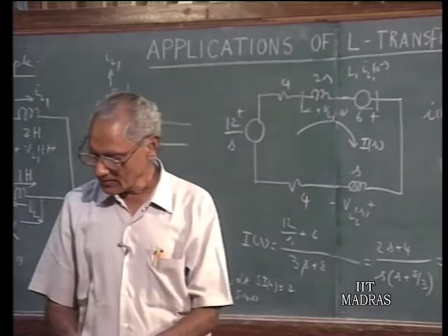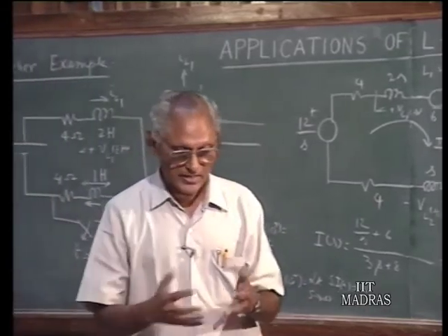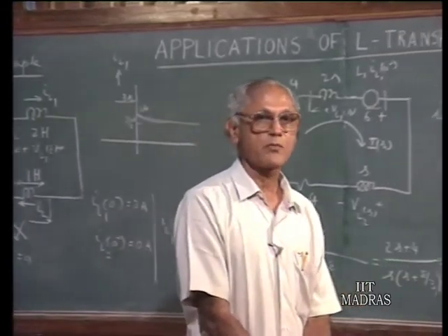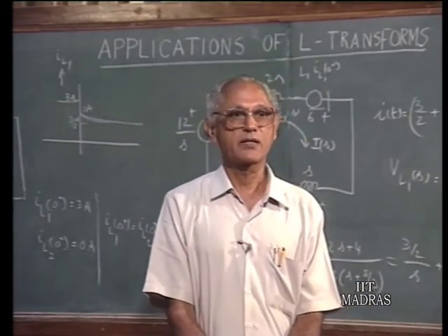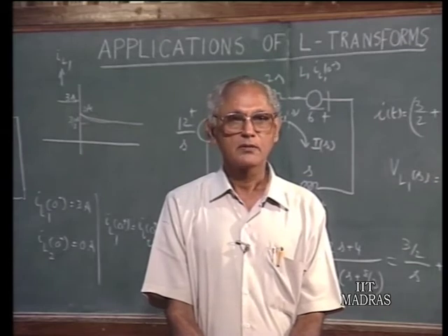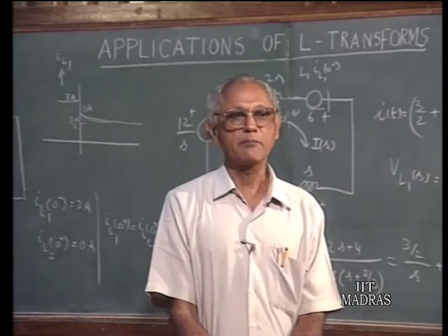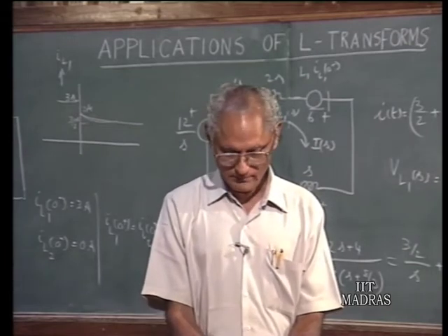But at this time, from what we have seen, let us now see what are the advantages of the Laplace transform domain in the transient analysis of electrical networks. We find there are a number of advantages compared with the classical differential equation approach.